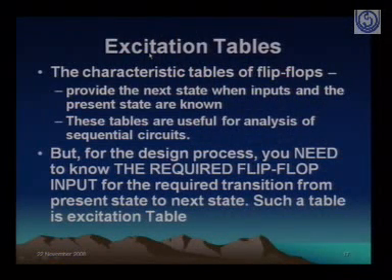Now one more thing we want to define about the flip-flop is called excitation tables. You must be wondering, we talked about the characteristic table. What does the characteristic table of flip-flops do? They provide the next state information: what will happen if the inputs S and R go to a particular state. These tables are useful for analysis of sequential circuits, but not for design. For the design process you need to know the required flip-flop input: what input should be put into the flip-flop for the required transition from present state to the next state.